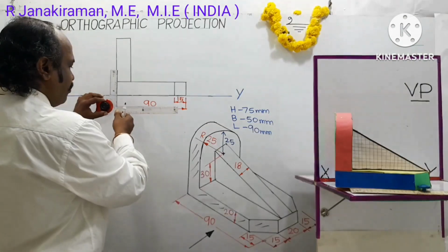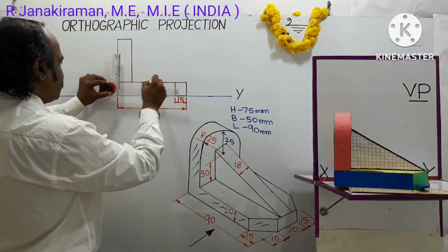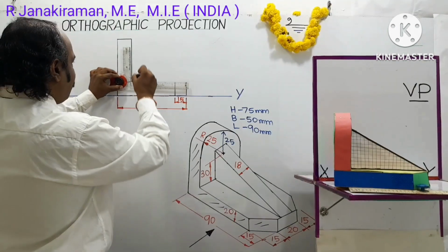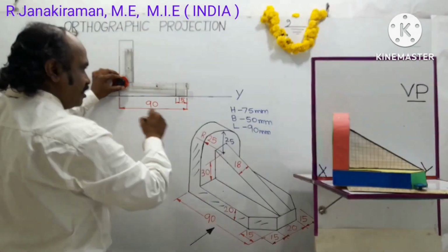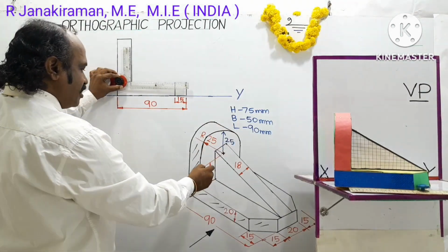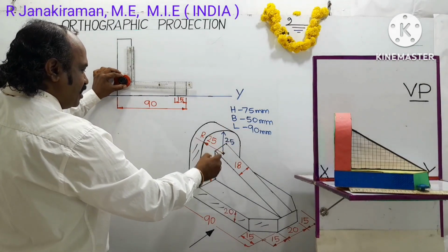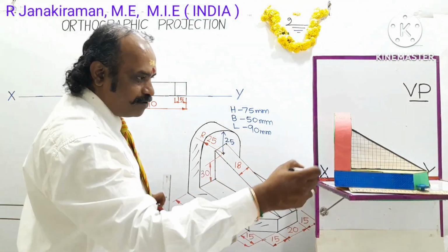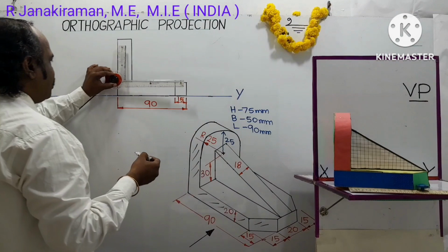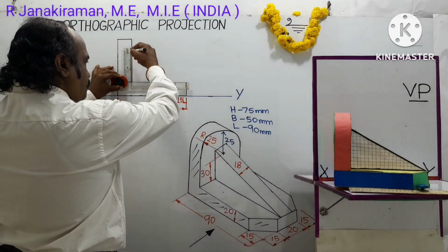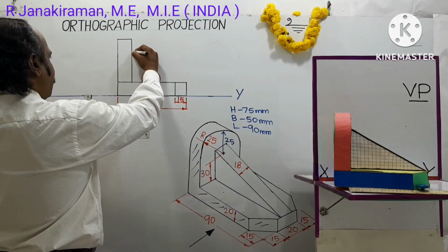Okay. So let me take 35 mm, more than 30. This is the top surface line, the top edge of the base. From that you mark a distance of 35 mm. 35 mm means 3.5 cm. This is the height of the center of the radial arc. This height is shown in the box-like graphical representation. This height is taken as more than 30. It may be taken as 35 mm. Okay. So this point is located.